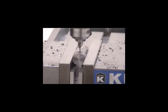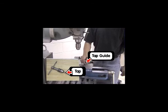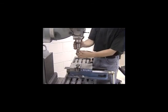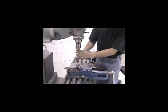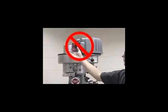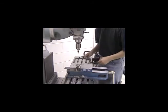For a tapped hole, first drill a pilot hole with the starter bit, then use a drill bit slightly smaller than the final tapped hole size. Finally, use a tap and a spring-loaded tap guide to tap the hole. The tap guide holds the taps centered on the hole and perpendicular to the part. While tapping, do not turn the mill on. Great unpleasantness will follow if you do.